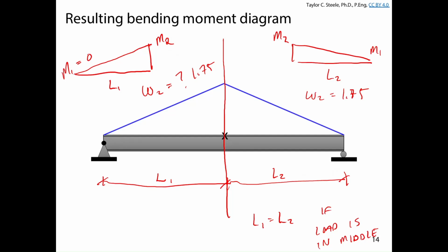And if we compare this to the example we did the other day, where we had uniform moment, M1 at the left, M2 at the right, and the full unbraced length of the beam equal to the length of the girder, basically we're increasing Mu by 75% just because the shape of the bending moment diagram is different, which seems perhaps weird at first glance.